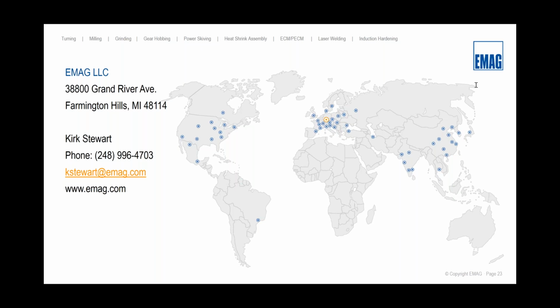once you've set up the part, it's always great to come back to the machine, load up that conveyor, and walk away. It means your green light's on, your spindle's turning, and you're making parts. The average Emag load unload time is only 8 seconds. So if you can load up a carousel with 20 parts with, again, a 20-minute buffer, that means your operator is doing other value-added work on another machine, whereas perhaps previously he had to stand by, manually load a machine, and be dedicated to just there.